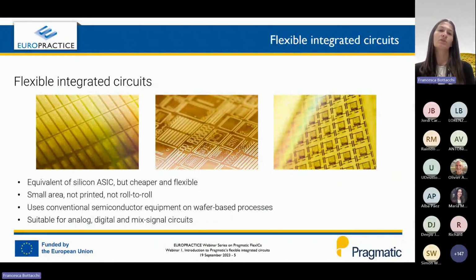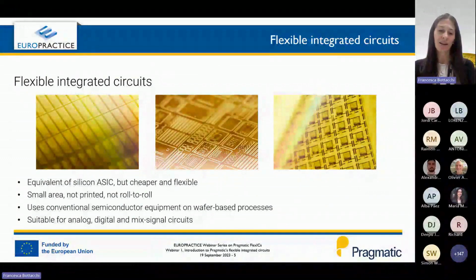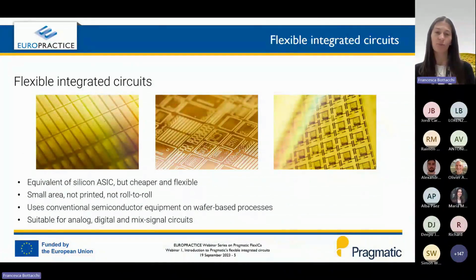This is because it uses conventional semiconductor equipment based on wafer processes, mainly using photolithography. But the biggest advantage is that it is suitable for analog, digital, and mixed signal. So you can really reproduce the circuit that you design on a silicon ASIC using a flexible integrated circuit.